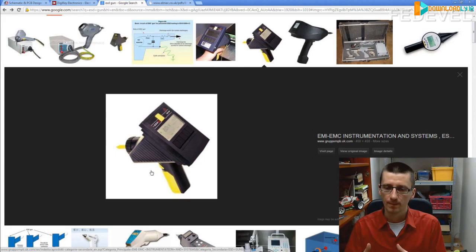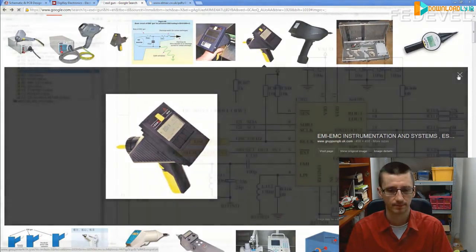So it's really a good idea to test your device for this ESD immunity. And that's it. It's really simple. Have a look. You can hire the gun, you don't have to buy it, and you can test your devices before you ship them to the customers or to the test house.